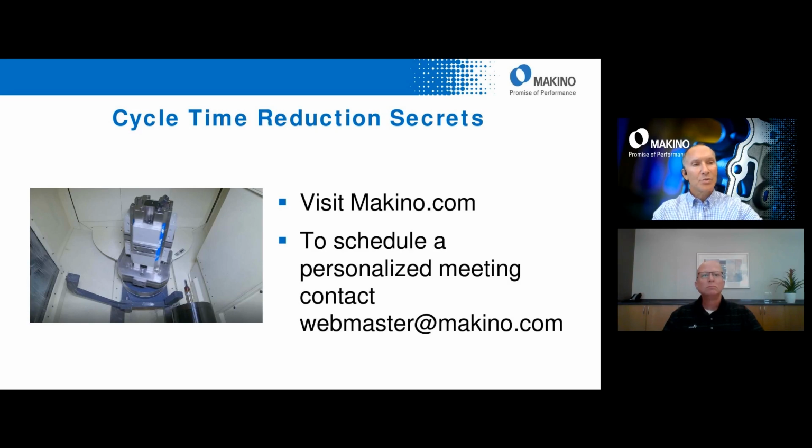Another question we have, Mike, is does M319 work on legacy Makino controls like the Pro 5? It does. It actually works all the way back to Pro 3. So Pro 3, Pro 5, and Pro 6. And I want to also point out that this is specifically for our A series horizontal machining centers. This is applicable to those machines.